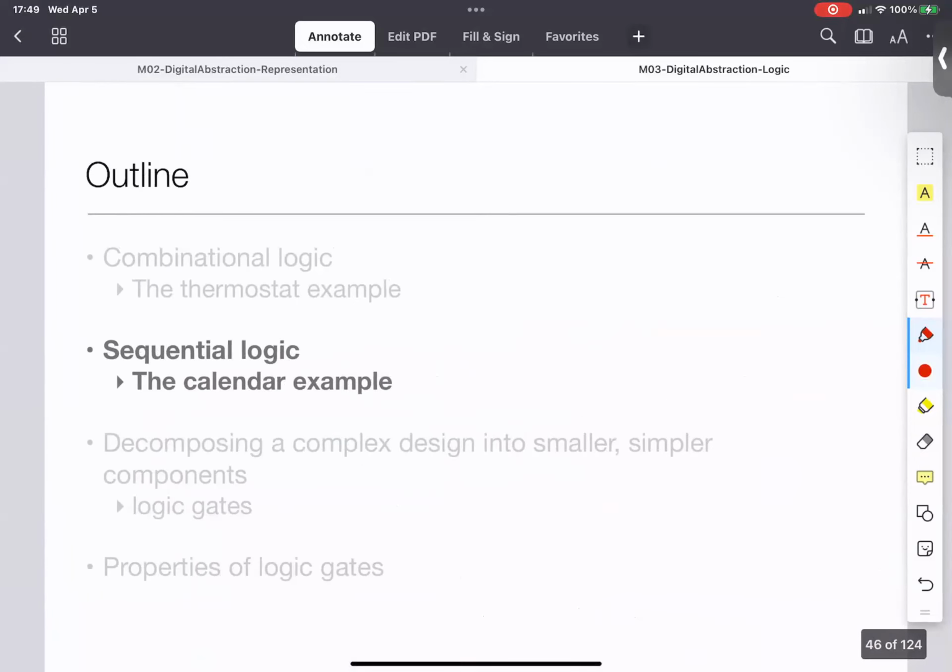Just to recap in the remaining few seconds: combinational logic depends only on the current input, with no memory of the past. We can express it as a logic equation, as a truth table, or as some sort of software pseudocode. There are a variety of different ways one can express it. Common to all of them is the fact that the current output depends solely on the current input. We are going to go into sequential logic on Monday.